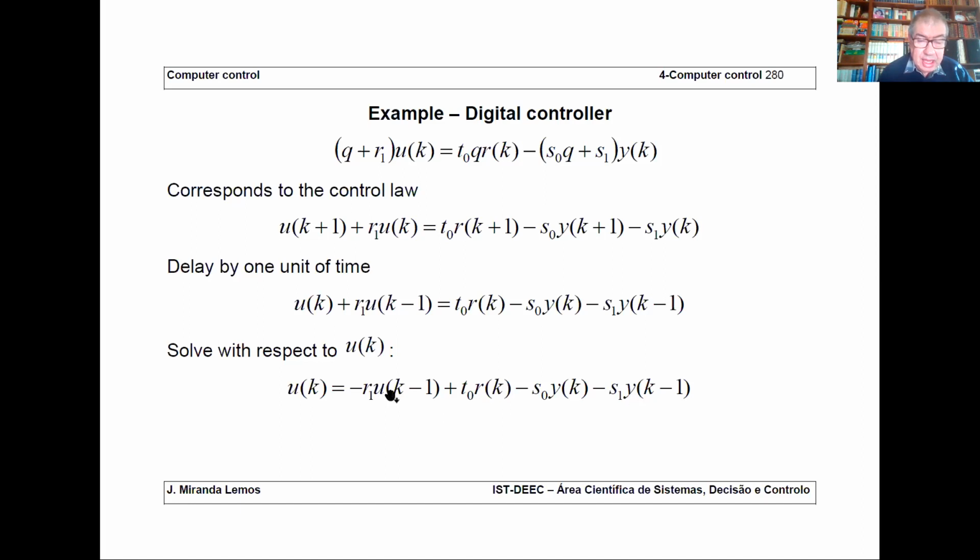Okay, so this is not arbitrary, it's your controller. And you do a linear combination of these signals. So the only operations that you have to do are to recall signals from the memory, read signals from AD, and then multiply signals by constants that you have previously computed.